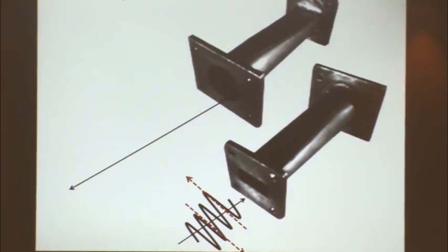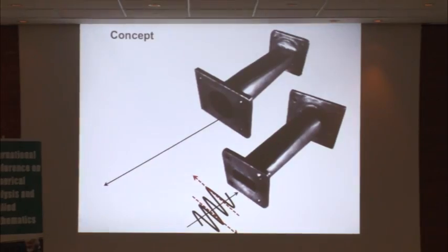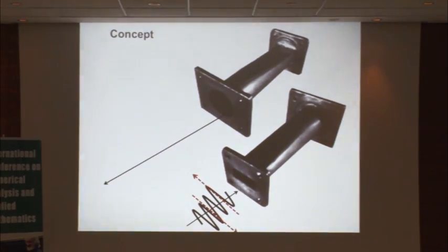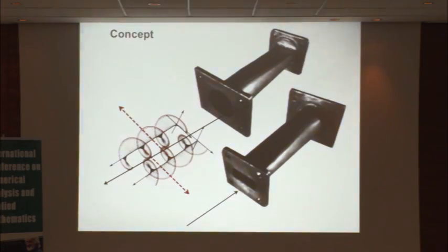And regarding your question in terms of polarization, I have to point out, just for the sake of completeness, that the input is a rectangular waveguide. But since I have this copper tube, I have an adapter, and this adapter changes the linearly polarized wave to a circular wave. But just for the sake of completeness, that doesn't really change anything regarding the tunneling principle.